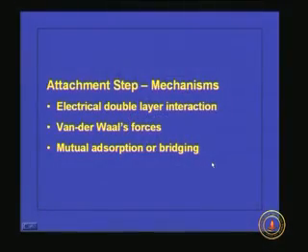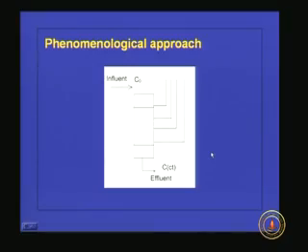The particles are getting destabilized because of the chemical reactions that we have seen earlier, and once the destabilized particle comes through the filter, it will be removed because of all these mechanisms. So, it is always better to add coagulant dose when we go for direct filtration to improve the efficiency, because the mechanisms are like this.